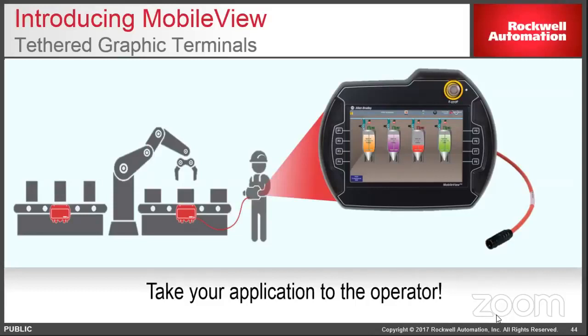It's a little bit different than a normal panel view, because usually you would have to add the buttons and e-stop and all that to your solution. So this is all kind of all in one. Another way to look at it is for long machines where, instead of having multiple panel views on it, and I hope you use multiple panel views, but in case that doesn't work out for you, you can actually just move this thing around to different parts of the machine. You have to have both hands on or just one? There's a single enabling element there on the back. So it's a 3-position switch.